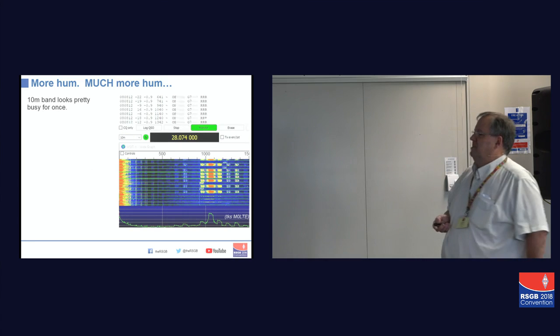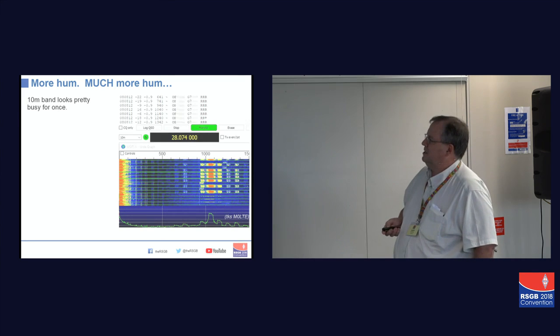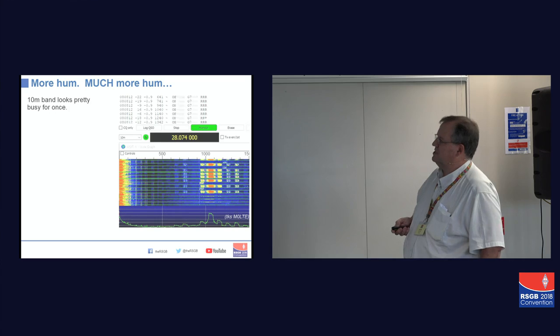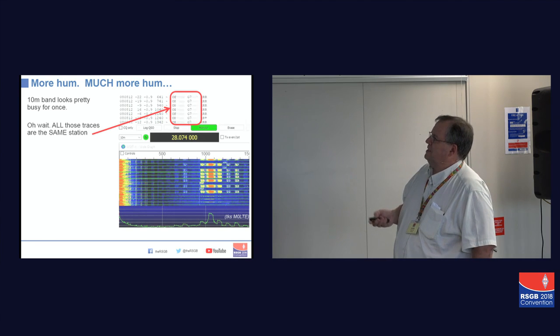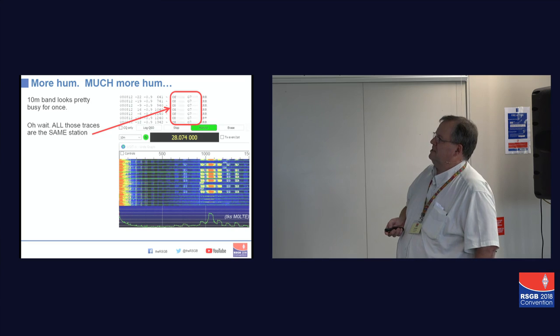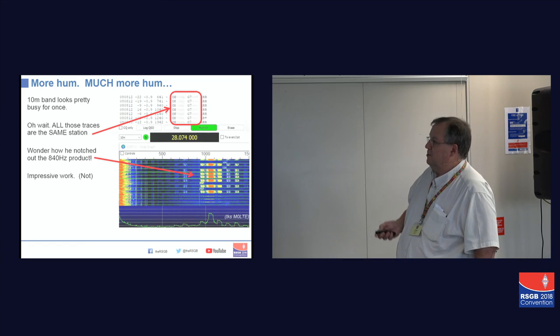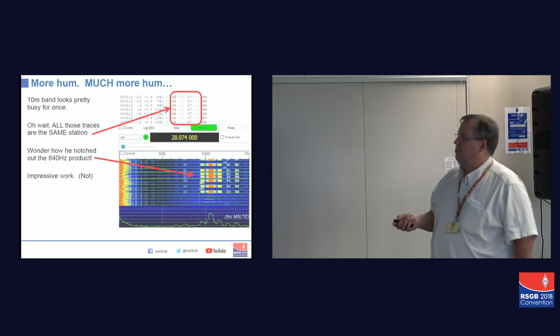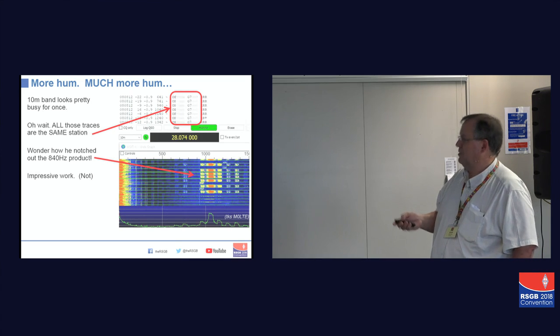This one was even more interesting. I don't know how he did quite manage to do this, but this was on 10 meters, and I thought, oh, the band looks remarkably busy. Tom, M0LTV, actually sent me this. Tom pointed out that actually they're all the same call signs, and actually those are all hum products, every single one of them, and it goes out as far, I think that one decoded, that one decoded. Later on, I think Tom actually managed to get a sniff of that one, so extraordinary, very impressive. We couldn't work out how he managed to notch out the one at 840 hertz. That was obviously something very clever.